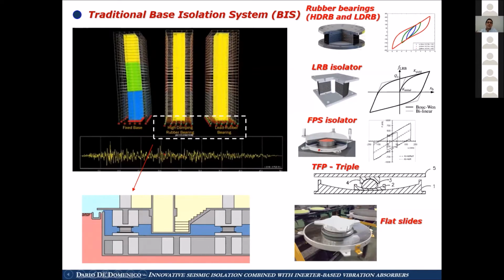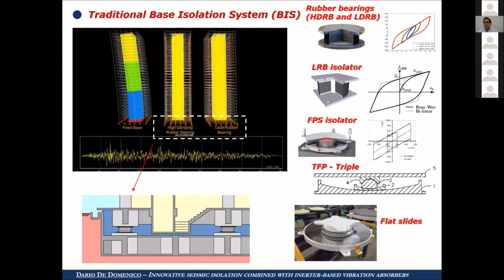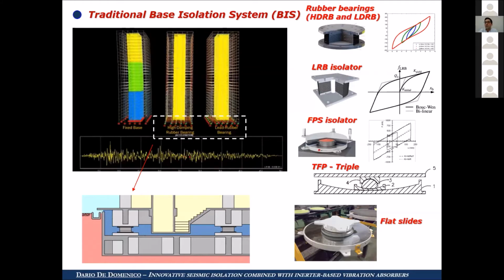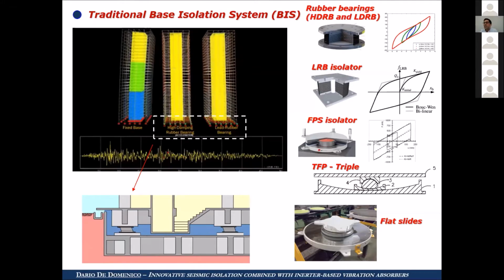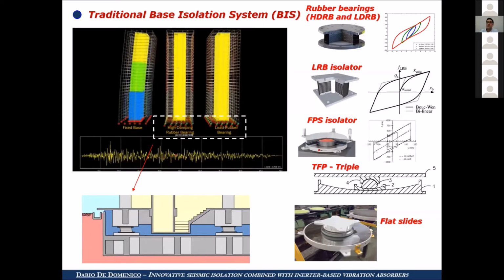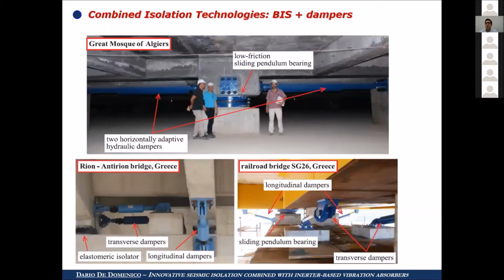All these technologies share a common underlying philosophy, that is to disconnect the motion of the substructure from the ground shaking by interposing a flexible layer in between the substructure and the foundation. Besides these traditional isolation technologies, there are also some combined isolation systems. I report here some examples taken from the web.